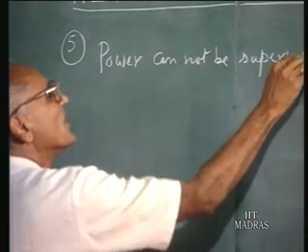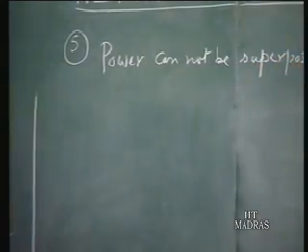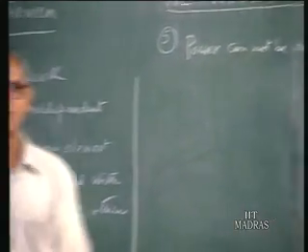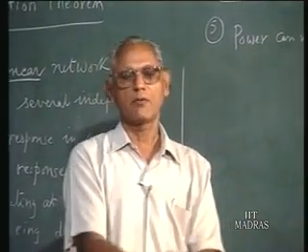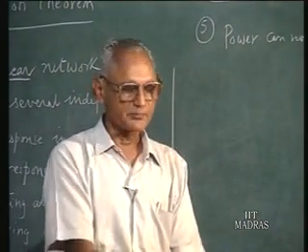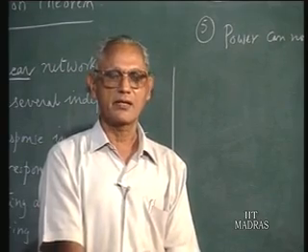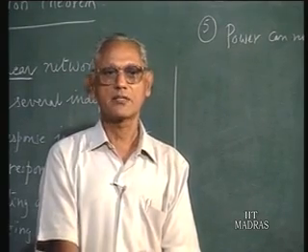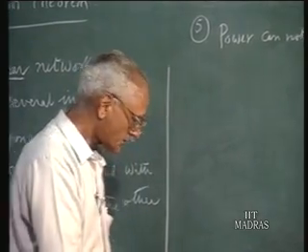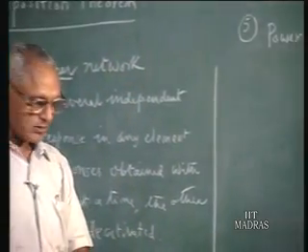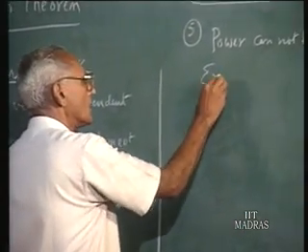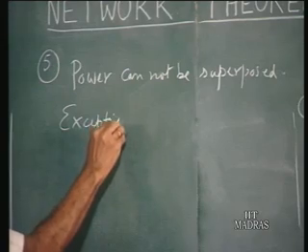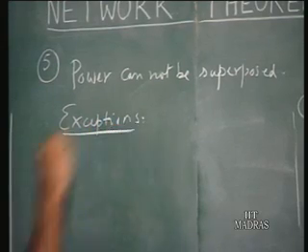In general, when you want to calculate the power in a particular element, you can't calculate the power due to each individual source at a time and add up the powers and say this is the total power when all the sources are acting at a time, because power is non-linearly related to a voltage or current, as the case may be. However, there are special exceptions to this, because in such cases the power can be superposed.